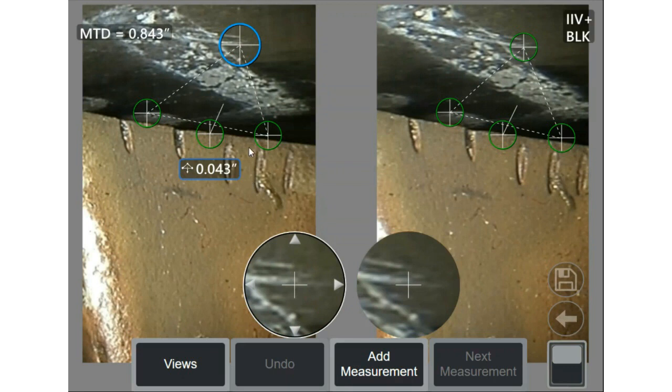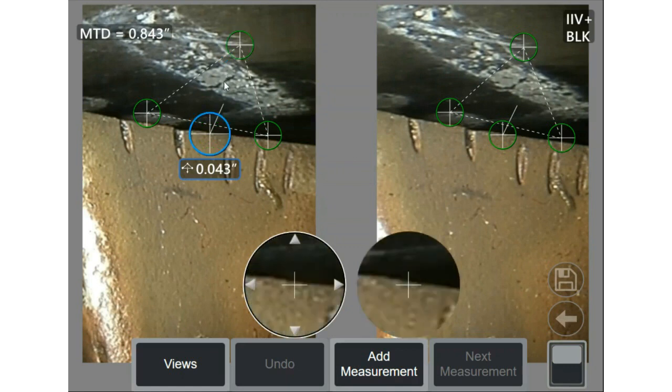And once I feel comfortable that my plane is established correctly on the shroud, I can then measure here at the tip of the blade. And when I look at this, I'm getting 43 thousandths from this point to this shroud, or to the mathematical plane that is on that shroud. Looks like I'm not quite on it, so I will click at 12 o'clock on this caret. 1, 2, 3, and in fact it changed 1/1000th of an inch, not a remarkable amount.